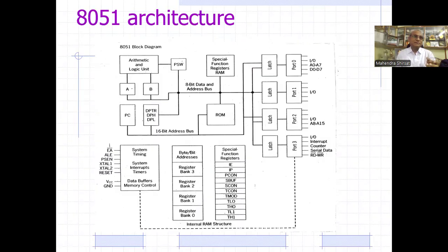That is why the concept of accumulator is there in the 8085 microprocessor, whereas in the 8086 we don't have that concept of accumulator. The concept of accumulator which was there in the 8085 microprocessor, the same concept is there in the 8051 microcontroller as well. Whatever addition, subtraction, multiplication, division, any arithmetic and logical operation we perform, the processed data is always stored in the accumulator.